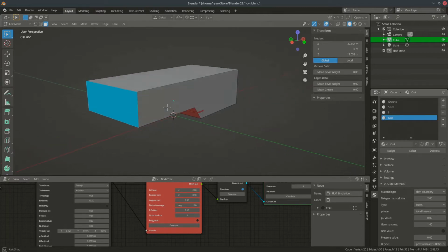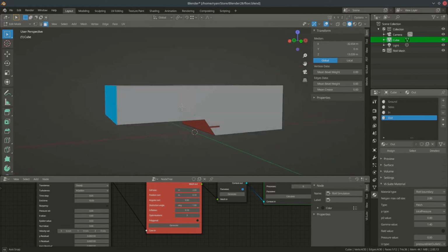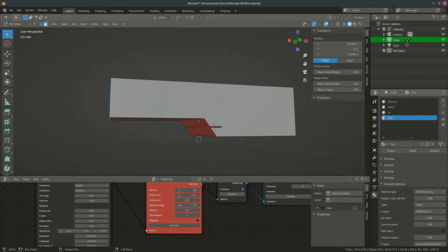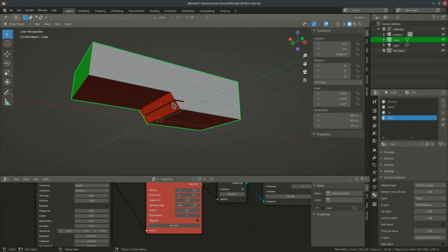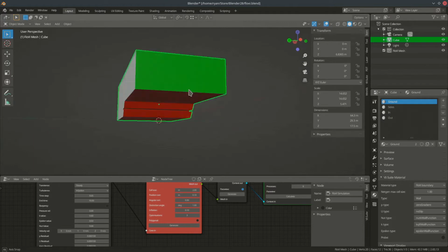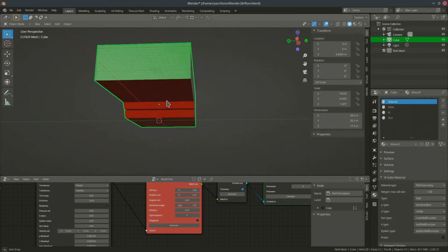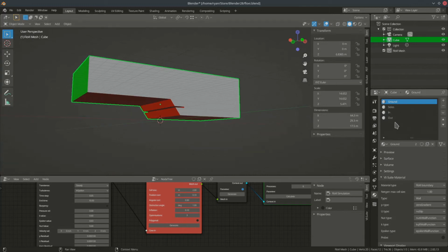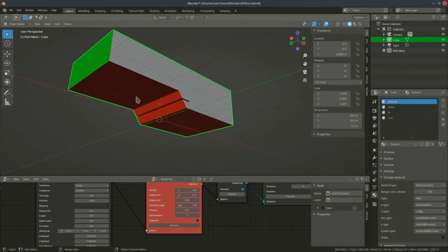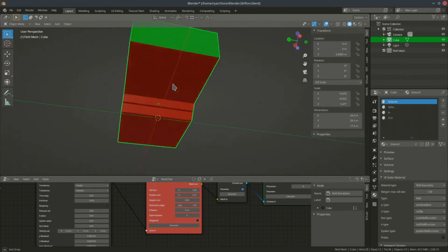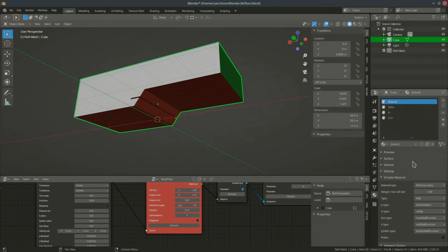So once you've set materials to the requisite faces, then we need to define what those materials are, or what they mean in terms of OpenFOAM and in terms of an OpenFOAM boundary condition. So let's take the ground first, and I've just coloured them so that you can see. It can be useful to give them a colour so that you can see clearly where they've been associated in terms of your model.